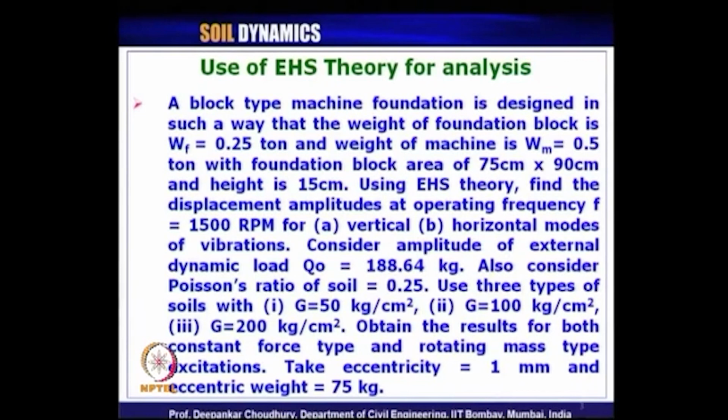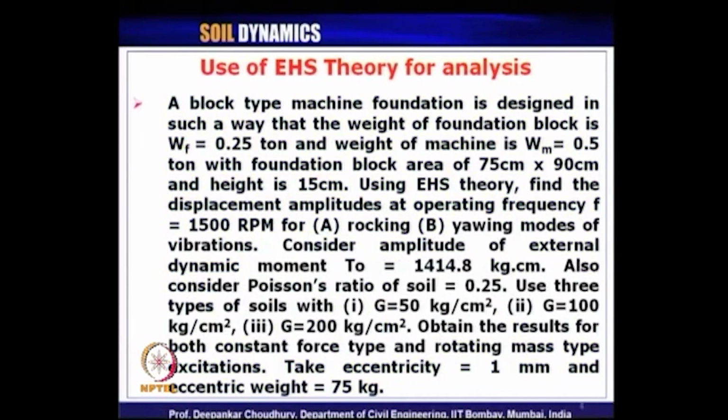We had seen the application of EHS theory for the analysis of design of machine foundation to compute the displacement amplitude at operating frequency for vertical mode and horizontal mode of vibration for block type machine foundation for 3 different types of soil in case of both types of excitations like constant force type and rotating mass type excitation. Also we have worked out the example for rocking.